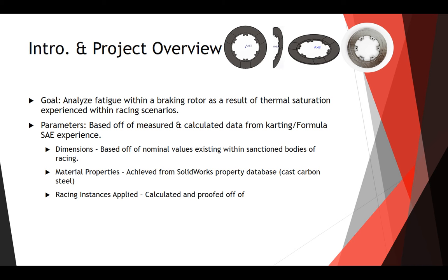Any parameters that I used were based off of measured and calculated data from my own karting experience as well as Formula SA experience here on campus. The dimensions of the rotors were based off nominal values existing within practice, and the material properties were all used within the SolidWorks and the Workbench database.